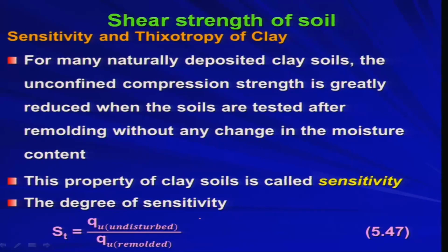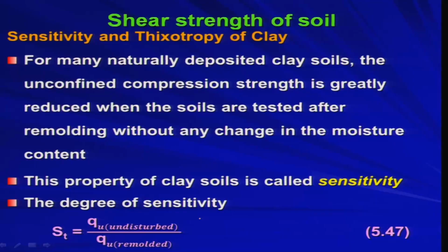Now, we will be learning two very important terms: one is the sensitivity of soil, another one is the thixotropy of clay. For many naturally deposited clay soils, the unconfined compression strength is greatly reduced when the soils are tested after remolding without any change in the moisture content. Now, what does it mean? Suppose you have clay soil in the field, now you are collecting the soil sample from the field, and then you are doing some unconfined compression strength test in the laboratory.